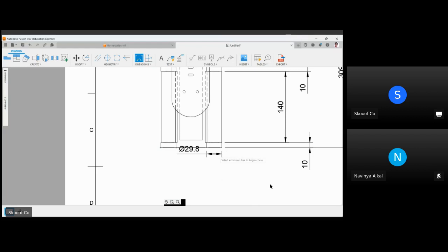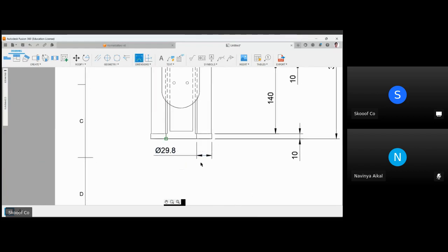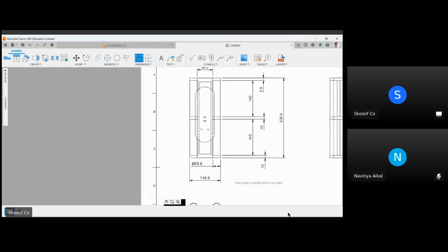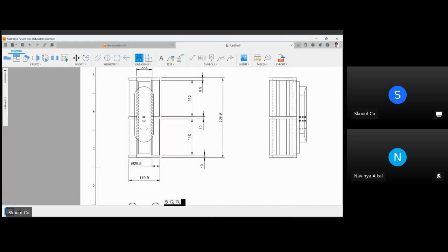Okay. So what you can do is directly put the text as cross to after this one, right? You can just drag it a bit right here, and put a cross to here in the text box. Again, we will put a hole dimension. You can click the corners if you cannot click the whole edge. Okay, so like this we can do.